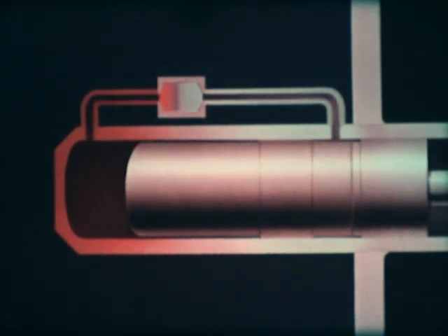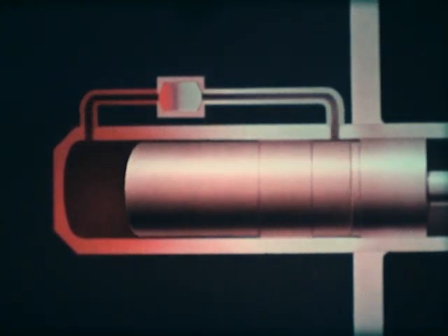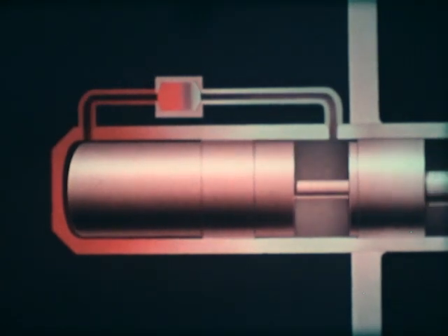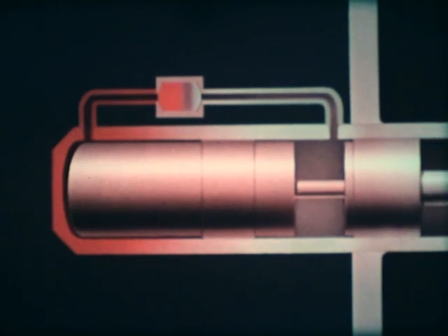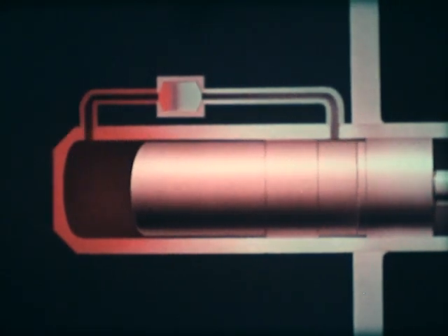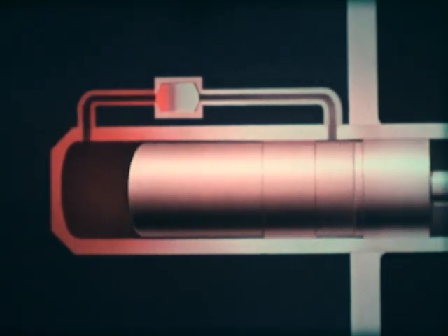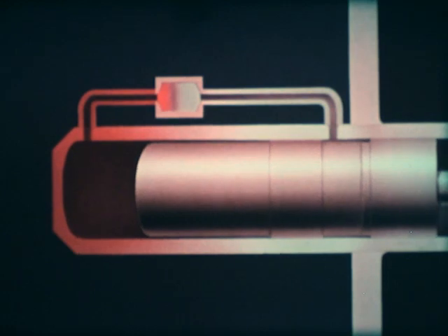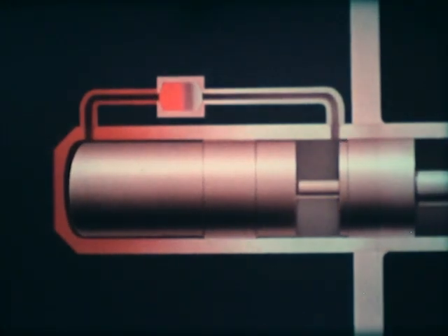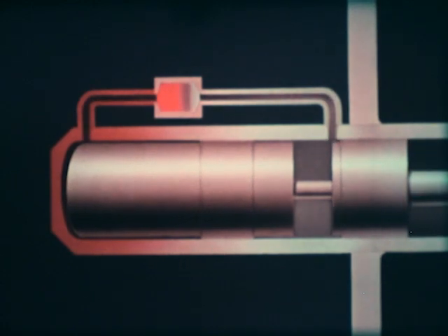There now remains only one essential reason to supply heat to the cylinder head, and that is to compensate for the tendency of the gas to cool during expansion. Conversely, there is only one reason to remove heat from the other end, which is to compensate for the tendency of the gas to heat up when compressed. Thus, the amount of heat to be supplied and the amount of heat to be removed is reduced to a minimum.